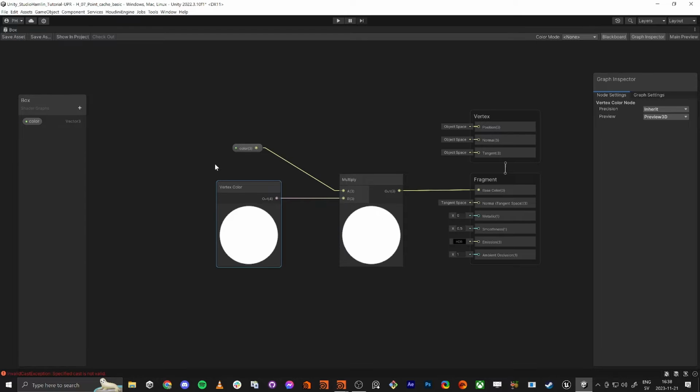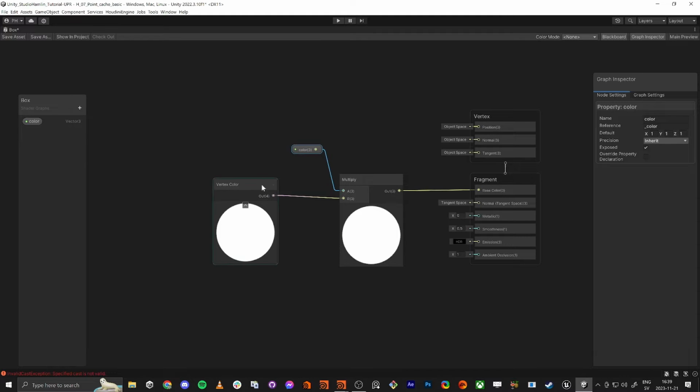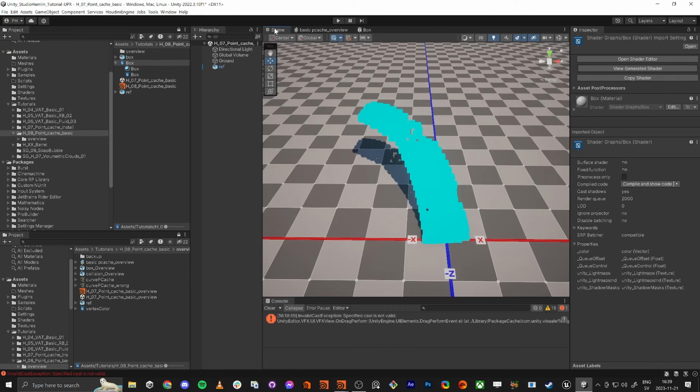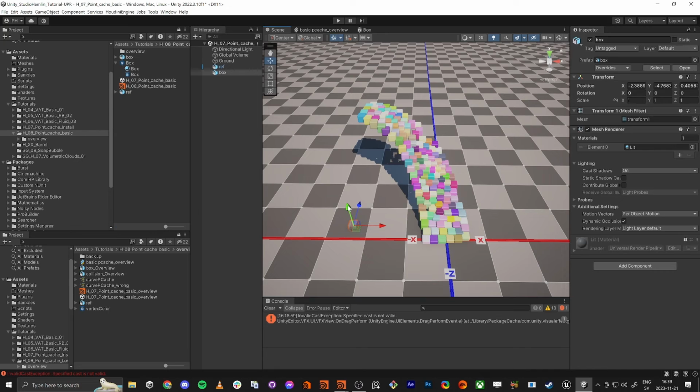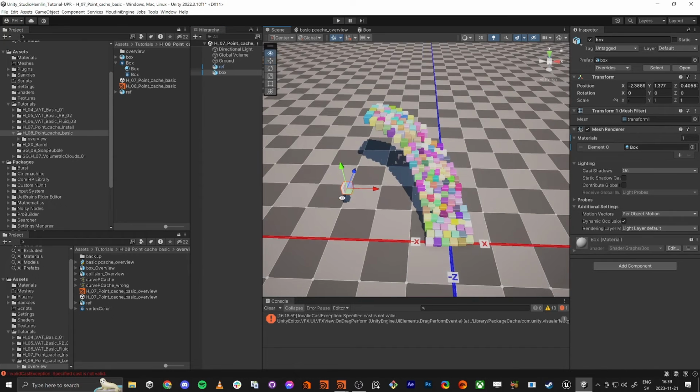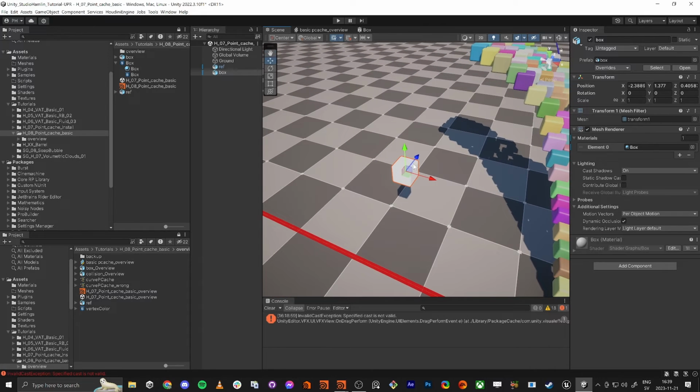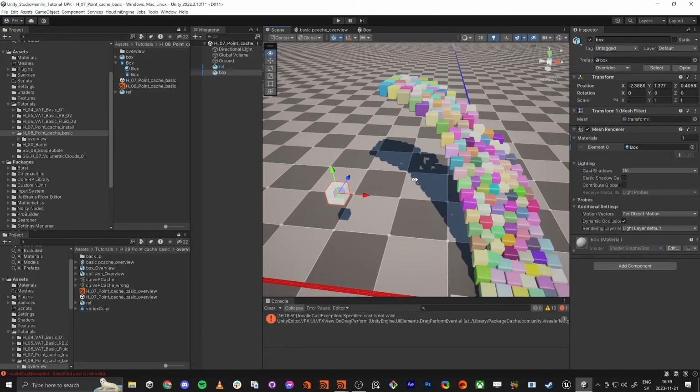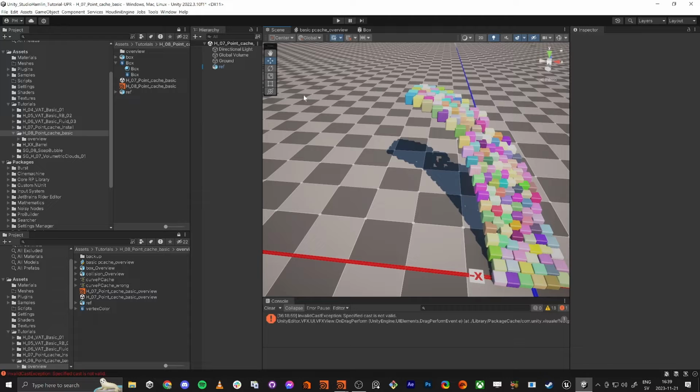And save. So what will happen is, the default is white here, so this one will never override. You see the colors here, right? And we can use this one later, because when we use it as a box here, this one will be white. So whatever color we multiply with white will be the color. So that's why we can use the same material for both the VFX and the static mesh.